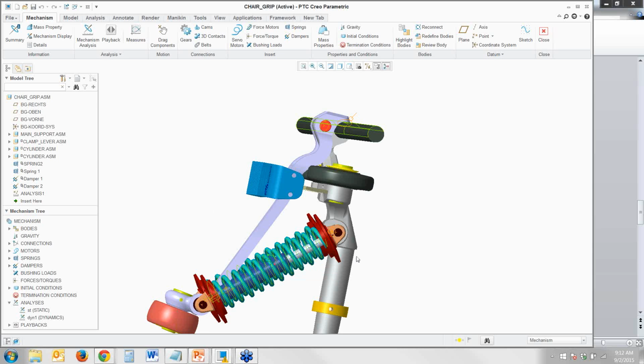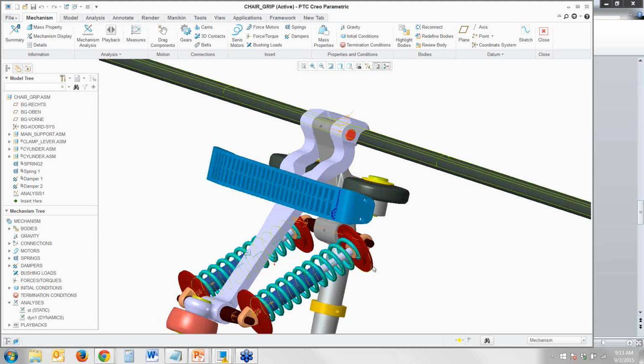We've already mentioned that we don't want this thing to be too strong, where it frays the rope, and we don't want it to be too weak either. Our engineers determined the optimal gripping force is 2,500 newtons. Right now we're at 3928, so we're much higher than we want to be, and we want to tone it down.